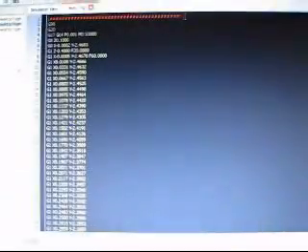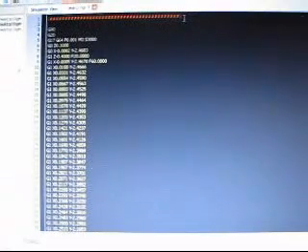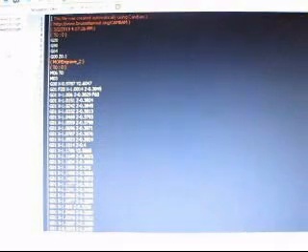Into clean 2, I'm going to put T1 space M6. Okay, T1 just tells me that it's tool number 1. The M6 is that it's assigning a tool change to the program. I believe that's what it is. Don't quote me on that.